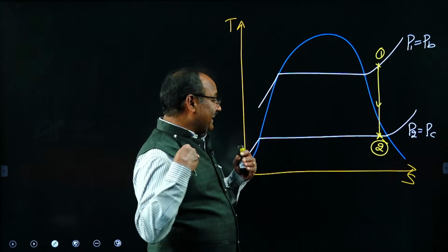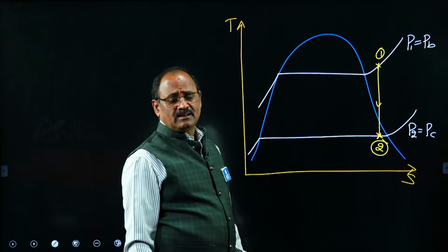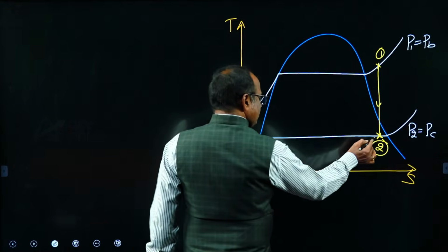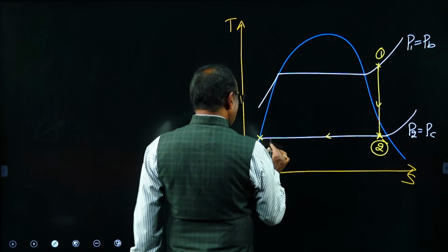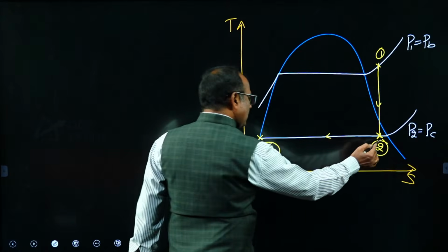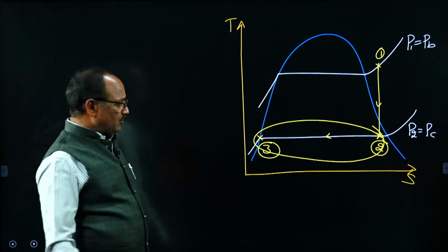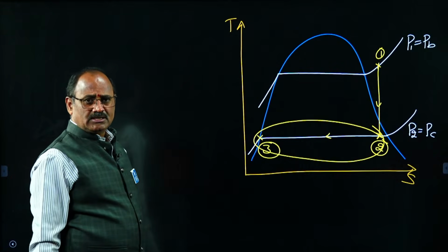That means, under any circumstances, moisture content at the exit of the turbine should not be more than 10%, right? Anyhow, this wet steam is entering the condenser where complete condensation is happening at constant pressure and constant temperature. That means these are condensation processes. That is the heat rejection process for a thermal power plant. In the entire heat rejection process, it is possible to maintain constant temperature.